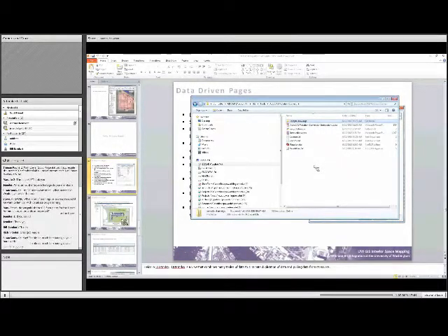We have been doing a fair amount of work with facilities on being able to track assets. And it actually has another component that we added into it for being able to do this using the Esri Attribute Assistant, which has just been an amazing capability. So let's bring this up real quick. With this, I imported a bunch of assets based on the building and room number that was stored in the asset management system, and just created a point in the middle of the room.